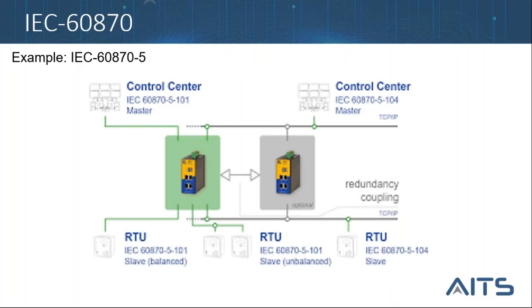IEC protocol is the protocol created by the International Electrotechnical Commission, which is a standard that defines systems used for telecontrol. Such systems are used for controlling electric power transmission grids and other geographically widespread control systems. For example, the IEC 60870-5-104 enables communication between control station and substations via a standard TCP/IP network. The TCP protocol is used for connection-oriented secure data transmission.